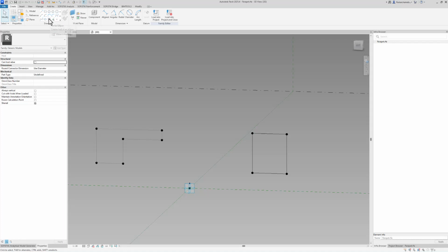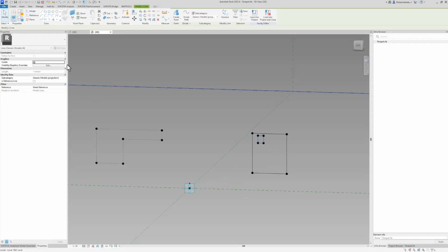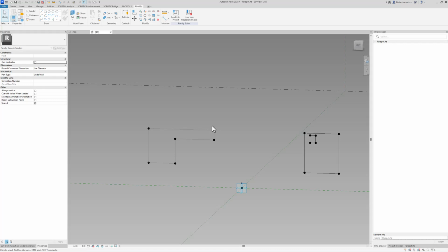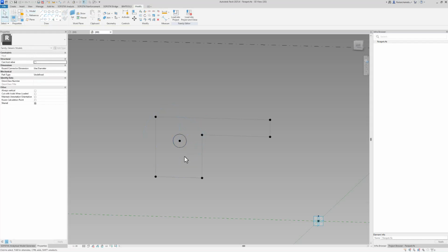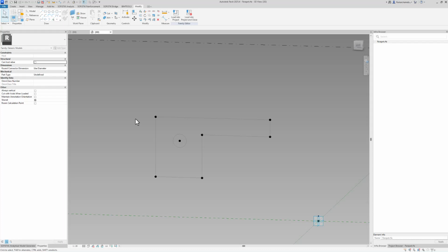One way to create an opening is to simply select a new boundary and place it within the already existing boundary. Keep in mind to also assign the visibility settings to it. So this one should be active when right is active. With the left parapet, I want to assign a circular opening. Keep in mind that circular openings need to be created as two half circles. I first create a reference point and I create two center arcs on it to represent my circular opening. And I select it to assign the visibility setting of left to it.